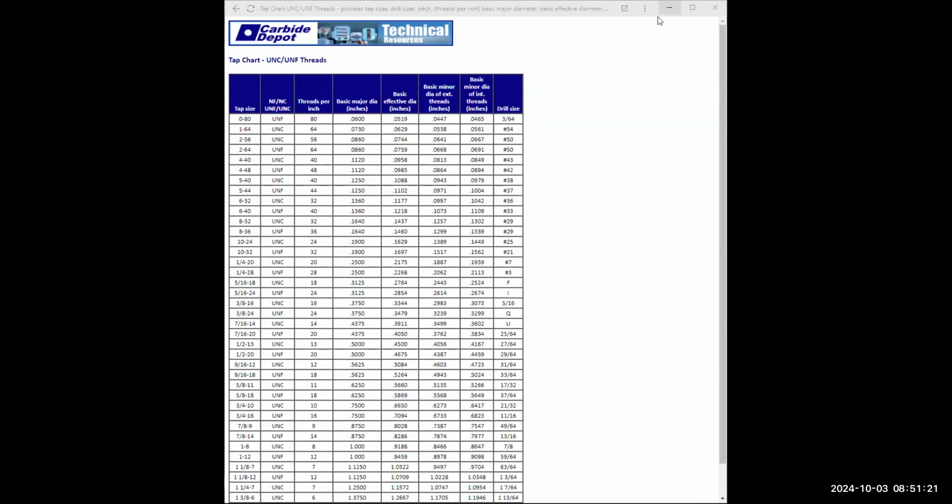Now, these little extras up here, we need to erase those. Type in the letter E for erase, enter, and I'm going to click on these lines.